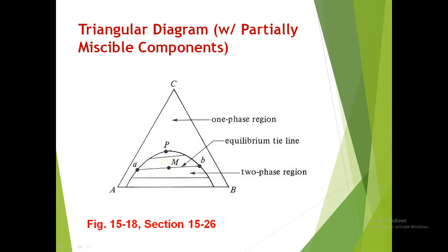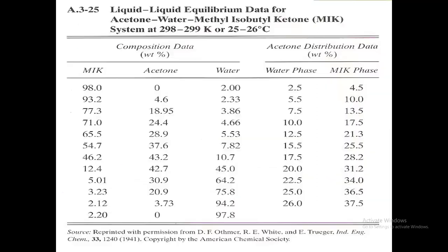You have this bulk phase M in the center, and this is your A and B connected by these tie lines. I will explain the tie lines later when we go to a bigger diagram. This is the plait point here. The plait point is that point wherein there won't be any separation anymore, in your feed phase and in your extract phase, solvent phase. So there won't be any separation already at the plait point. Now that's how it looks if you have partially miscible components.